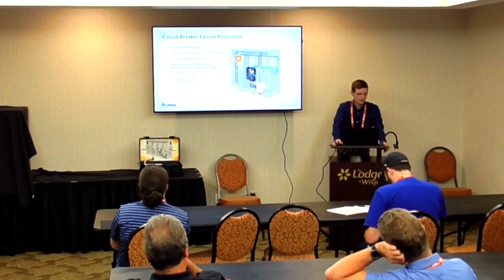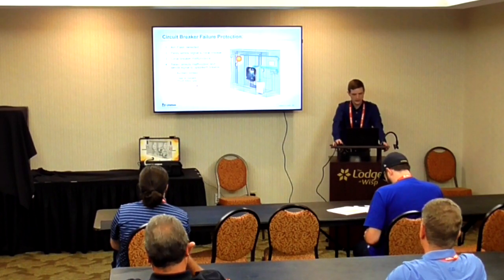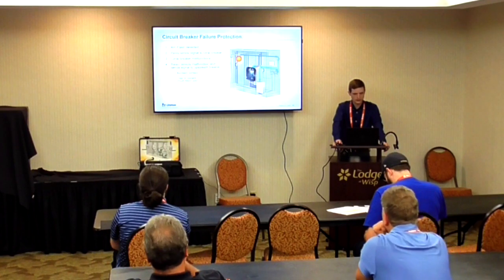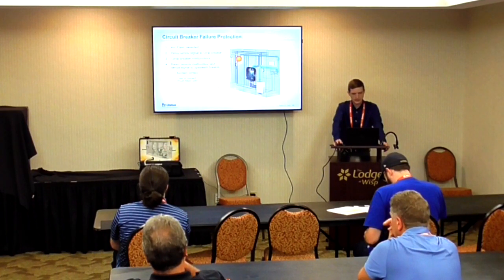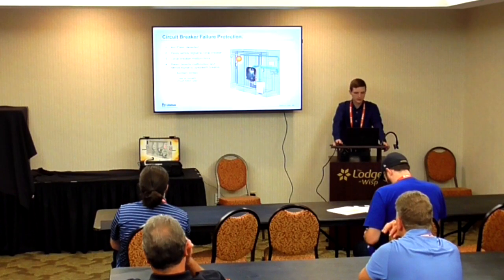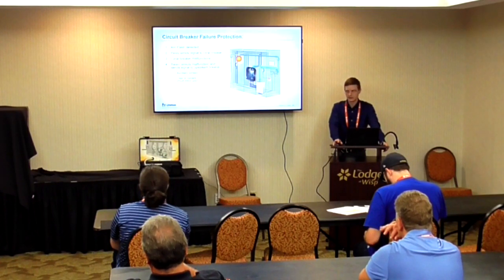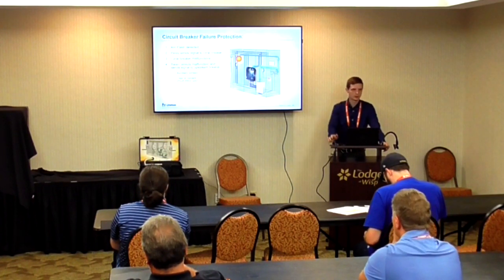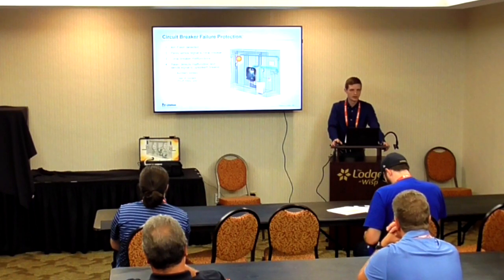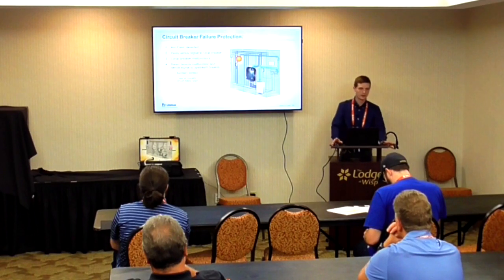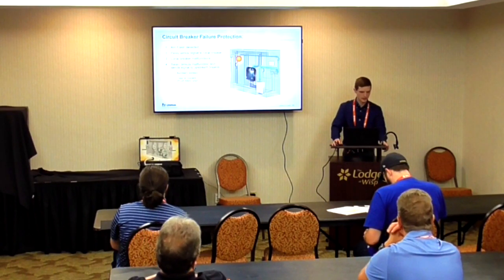Something I said is that some of these relays have some additional features. I'm not going to go on a wholesaling pitch, but some arc flash relays like our PGR 8800 do also have the ability to have a CT wired in, and that will just detect the loss of currents, just detecting unit health here. As well as prevents nuisance trip. So if you've got, let's go ahead and say a very dark enclosure normally, and then you open up and it's a bright sunny day out in Arizona, you don't want that to trip the relay. Now it does have to be above a certain lumen level anyways, but the CT is just an added level of nuisance protection.